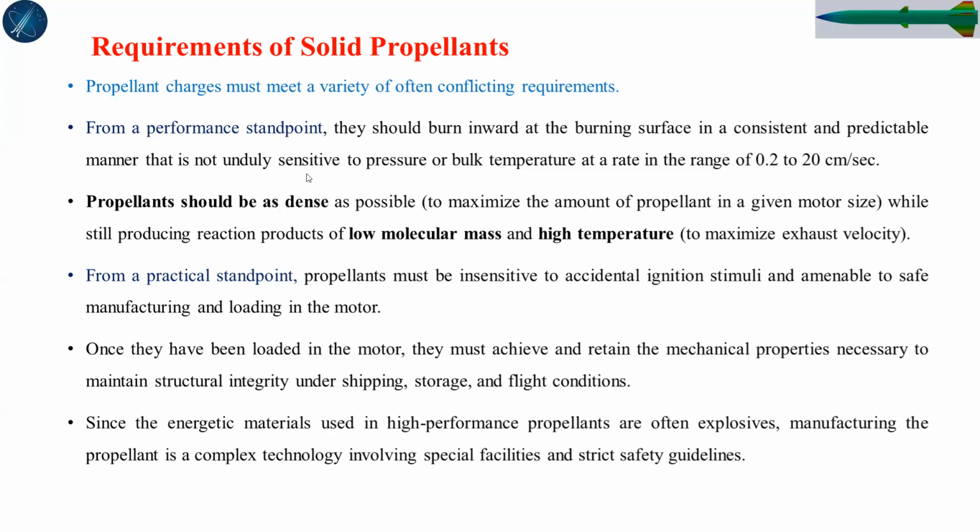That means a kind of regressive burning in a consistent and predictable manner, that is not unduly sensitive to pressure or bulk temperature, at a rate of 0.2 to 20 centimeters per second. That is called burning rate. The propellant burning rate should lie between 0.2 and 20 centimeters per second.